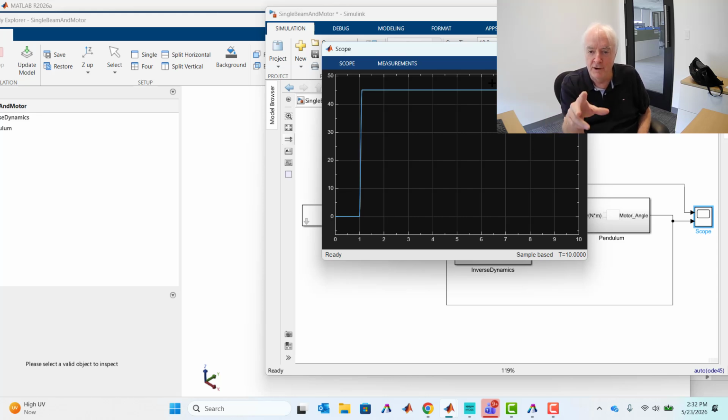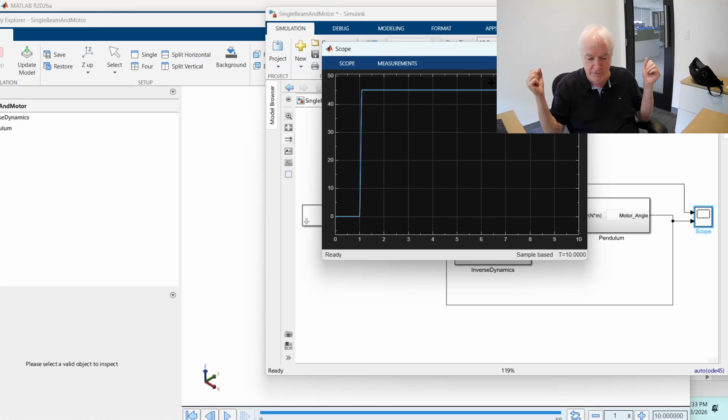And it's interesting to kind of look at these comparisons head to head. It's that basic idea that whenever you're applying feedback, you have to wait for the error to occur before the feedback mechanism does anything. You know that, again, PID's starting point is the error, and it takes the proper ratio of proportional, integral, and derivative actions on that error to come up with an ideal torque response.